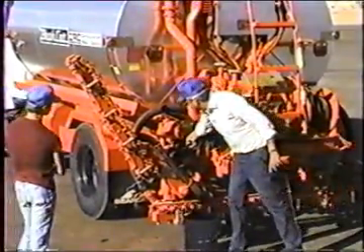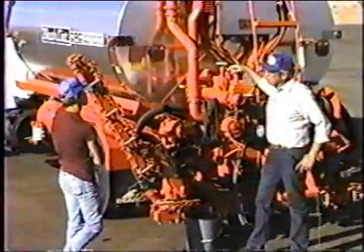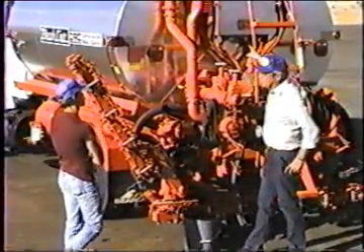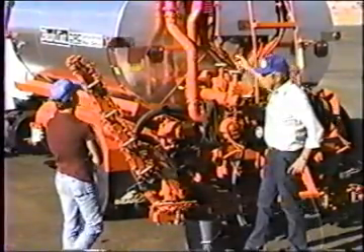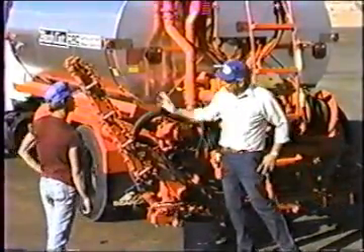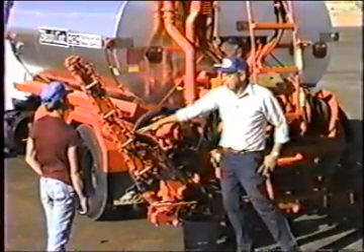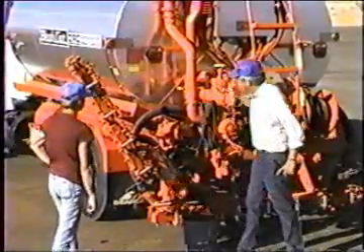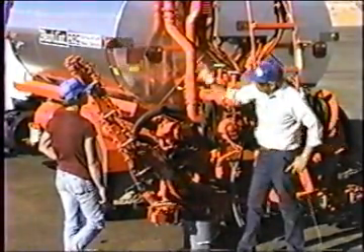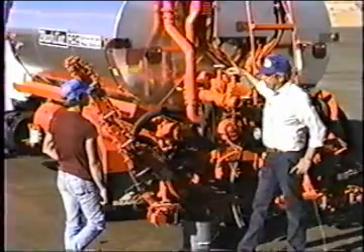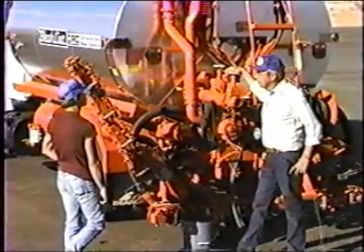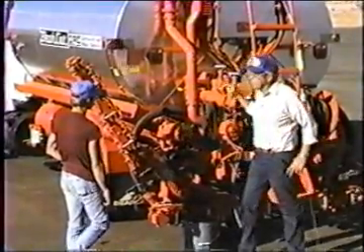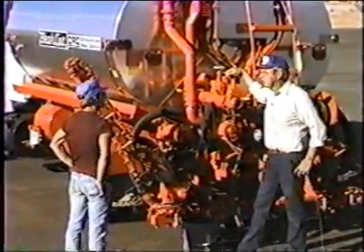Okay, the valve down on the side here is actually a double pilot check valve that won't let that fluid flow unless it is told to by the control valve. So in a nutshell, what that valve does is prevent that wing from drifting down if it's not being controlled by the control valve. If that valve isn't in there, it can actually leak through the control valve and the wing will drift down. If that happens out in the field, if you have a wing that drifts down, it's in the lockout valve, and it's just a matter of taking that lockout valve apart and cleaning it out.